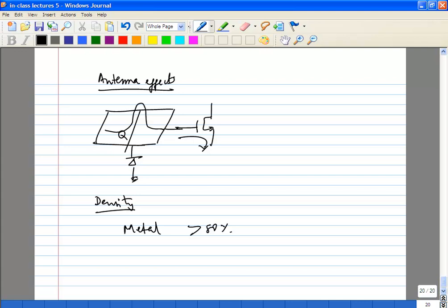So what you have to do is, obviously your circuit routings and everything are going to contribute maybe 10% or 15%, probably not much more. So if you want to make this up, you will typically have to do what is called fill for your transistors.